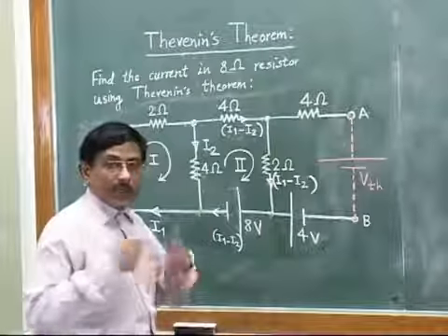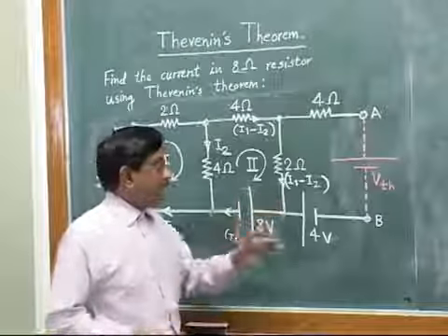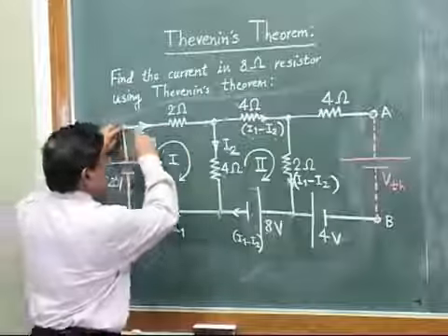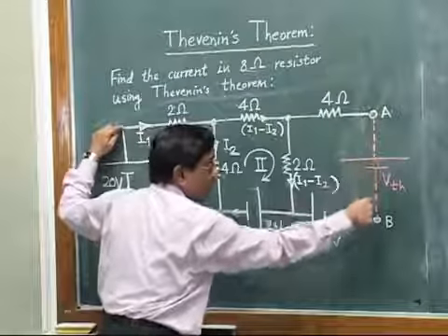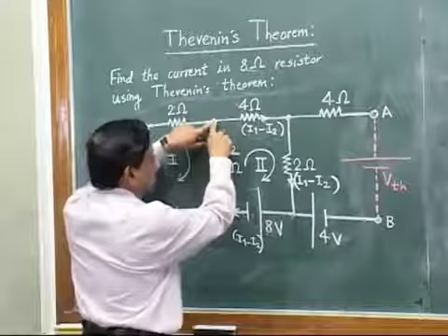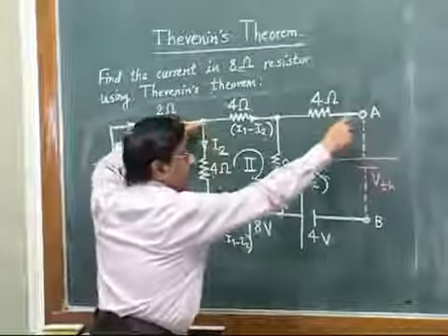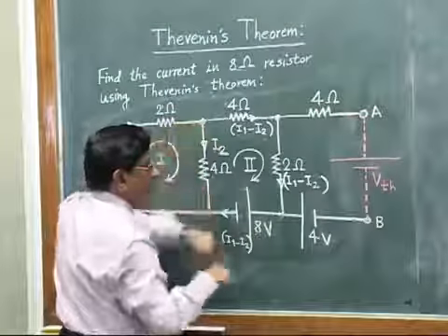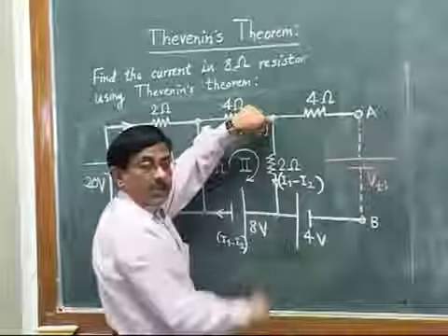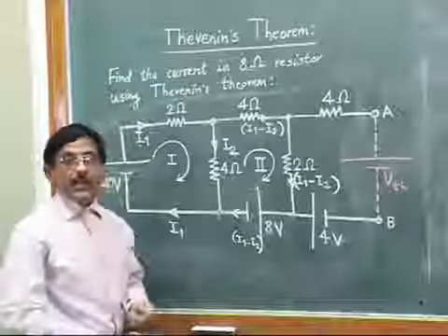Let us find out how many loops we get. We want any one, but let us see how many loops we get which will contain VTH. For example, I will take this entire full loop. See, VTH is covered. So this is one. Or I may cover from this point, this particular loop. Still it is covering this particular VTH. Or I may take this small loop. It is also covering the VTH. So I can get 3 such loops where VTH will be contained in the loop.